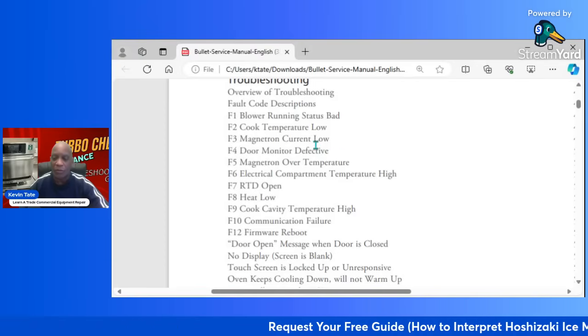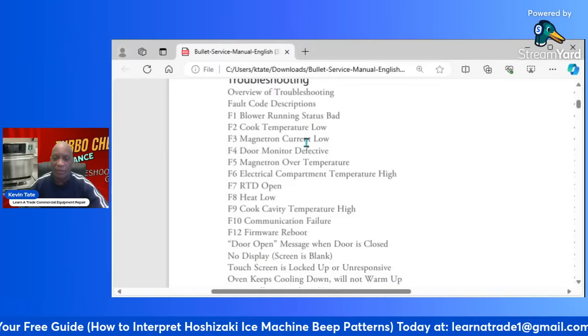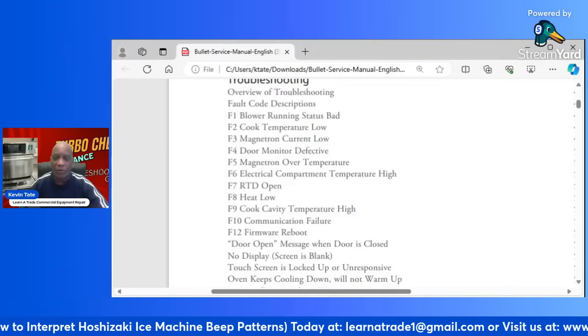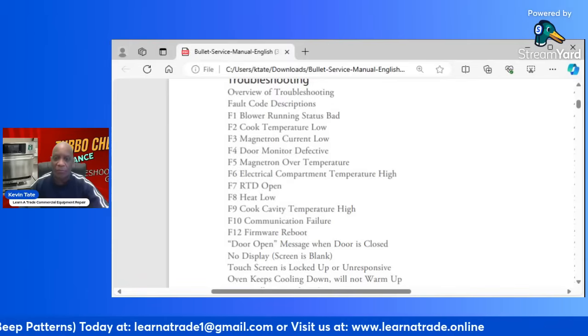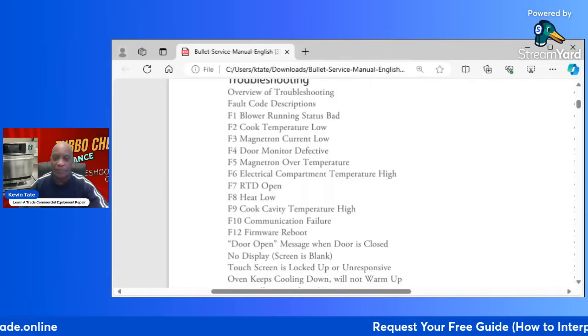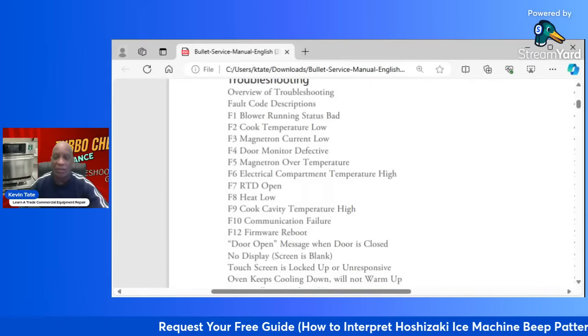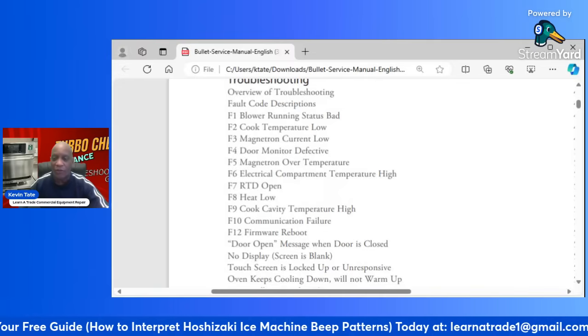So be aware of that, and know that's where you'll have to take some troubleshooting steps to find out what side is giving the problem. More than likely, it's one side and not the other. So you have 2 magnetrons, on your left and right. You have 2 filament transformers on your left and right. Then behind those, you have 2 high volt transformers on your left and right.